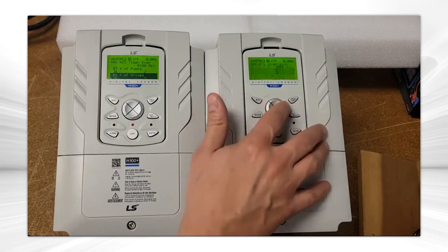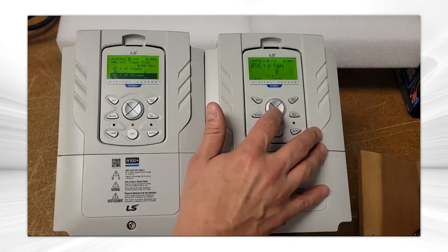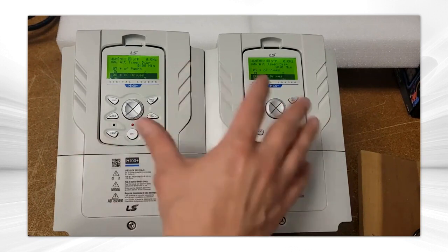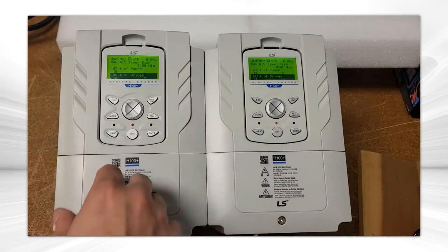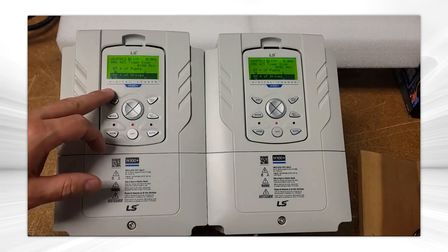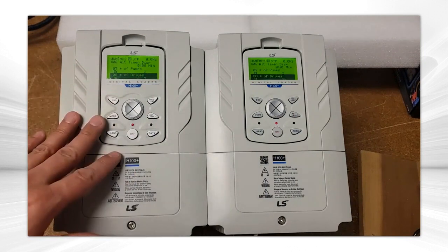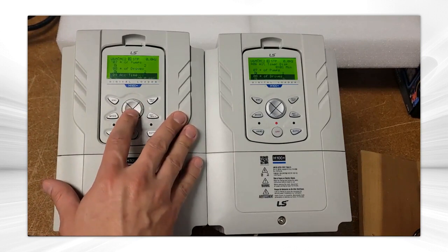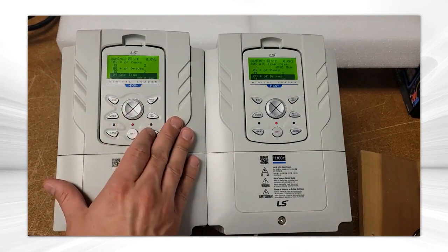I'm going to do the same on this one. So some of these parameters are data share. If you look at the table, whatever drive is the master drive, you'll see a plus on the top of the screen when you're in auto mode. If you program from that drive in the macro list, it's going to automatically send that parameter setting to the other drive. So that's advantageous to make setup a little bit easier.